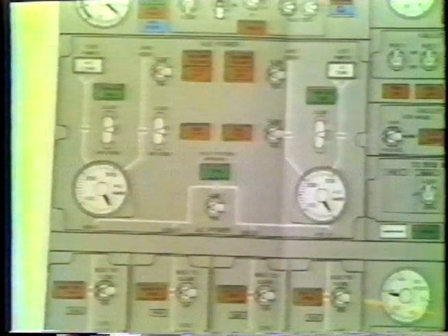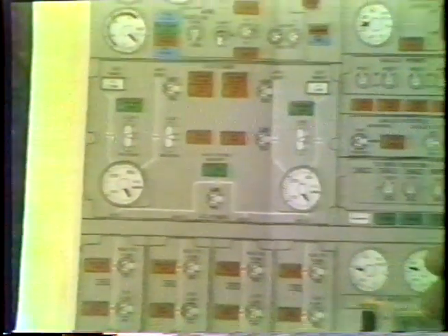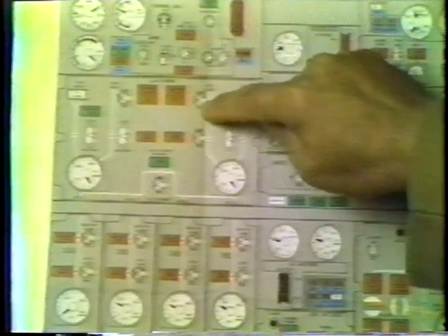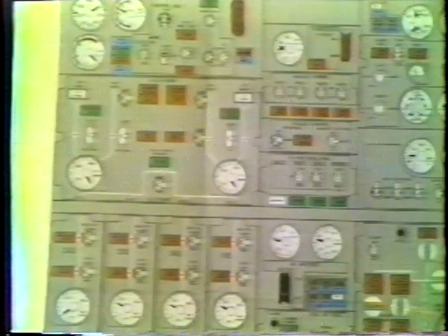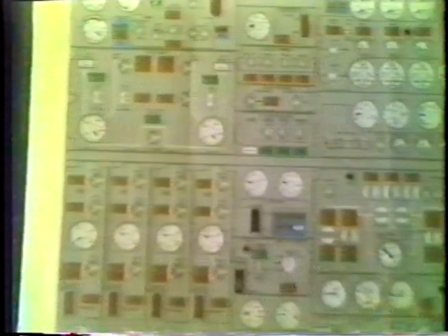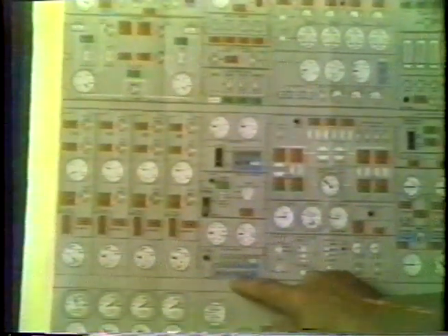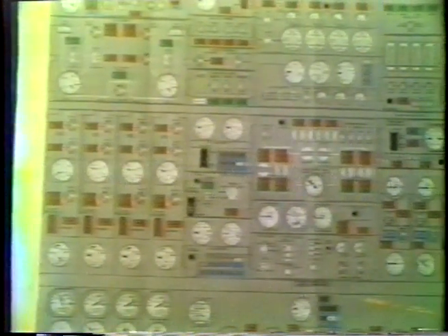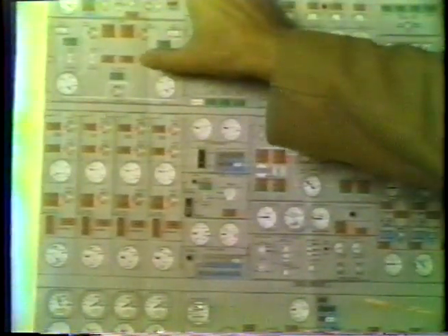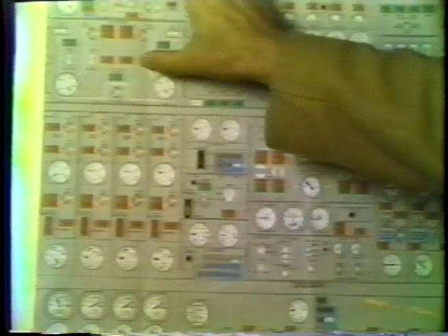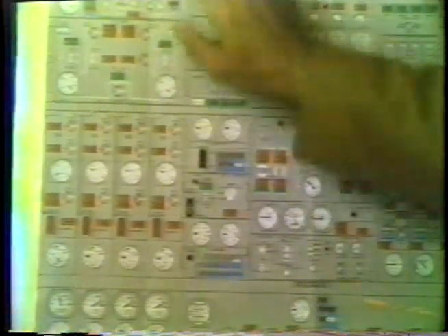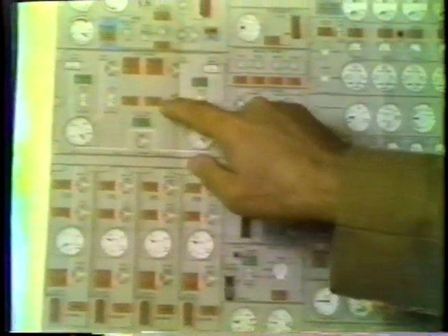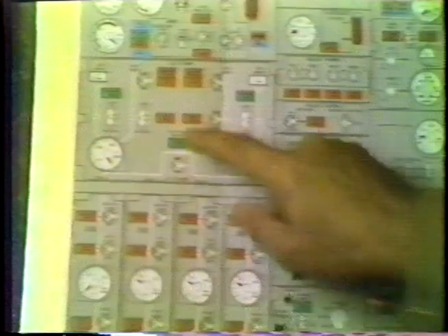If you wish to use the second APU generator, which is normal operation, again, closing the field on number 2 APU generator, you come down here, select number 2 APU meter button, and you can check the voltage and frequency on it. If it was proper, upon closing the generator breaker and APU, the first thing that would happen would be the split system breaker would automatically trip, and then the generator breaker would close.